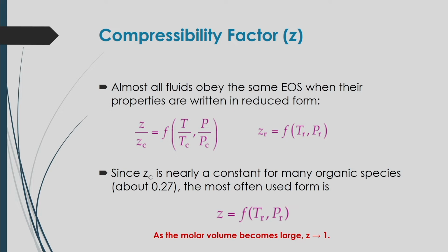In that case, the compressibility factor considered in real gas behavior should be expressed in terms of temperature and pressure at the critical condition. Almost all fluids obey the same equation of state when their properties are written in reduced form. What is that reduced form?